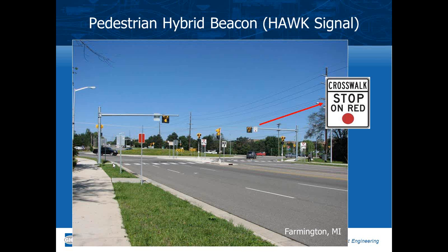The difficulty I have with this device is twofold. One, its placement in proximity to the entry and exit of the roundabout, and the challenge to the driver of having to process information from many different sources, and the confusion or the potential for error with the driver paying attention to one device and ignoring the other, or missing the pedestrian.